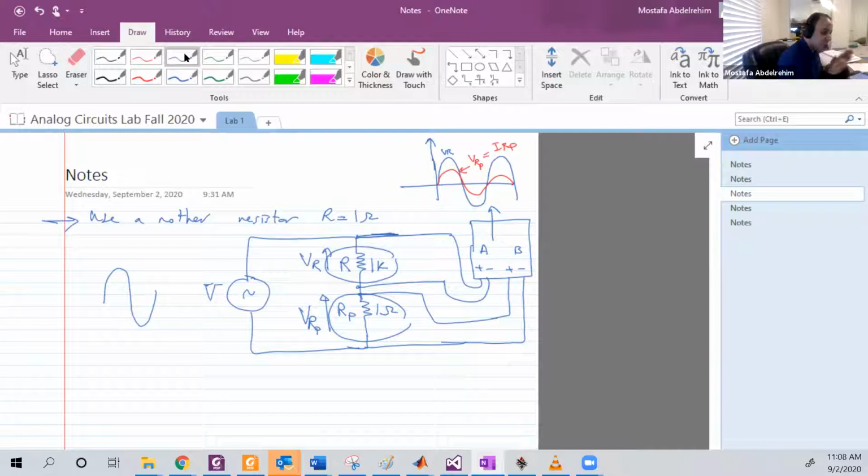All oscilloscopes have something called XY mode. What happens in this mode? The oscilloscope will not draw the 2 signals it has on channel A and channel B. It will do something very useful: it will draw them together.